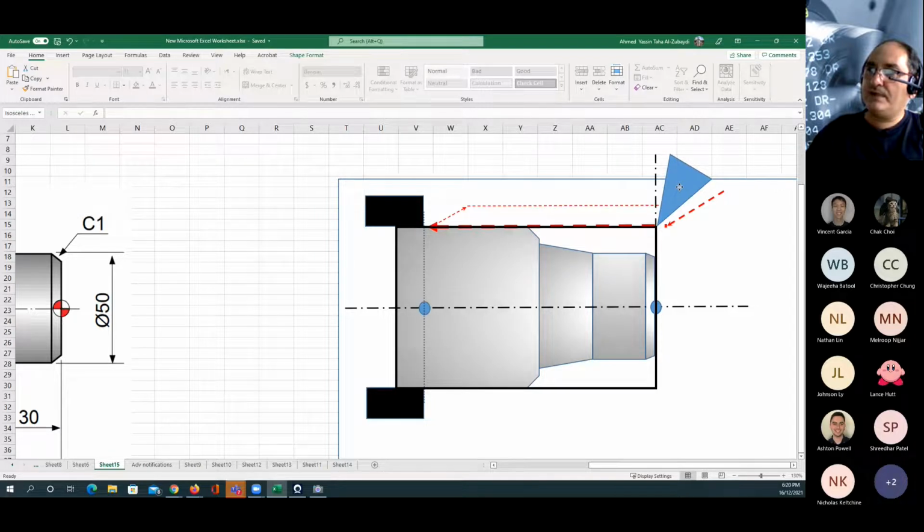For example, if the datum point is at the face of the finished work part, and we add something about 1 millimeter at the face, again to insert the cutting tool to the value where Z is equal to 0 and X is equal to the diameter, which is 70 millimeters. And then I'm going to say G01 to X equal to 0.